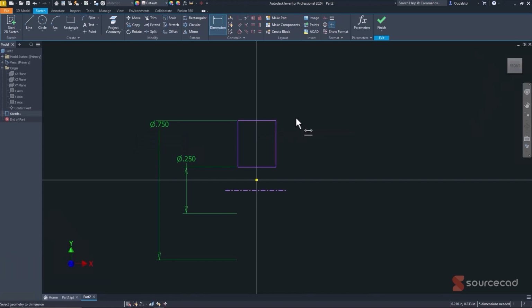And then what you might also want to do is actually put this center line on the midpoint. This is because, keeping in mind these origin planes that you have, they can be very useful later on in your extrusion or revolve for that matter. And it's a lot of help to know that they're there and how you can utilize them for your next sketches.